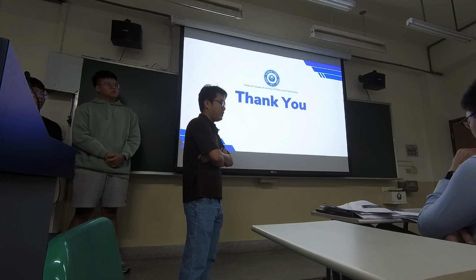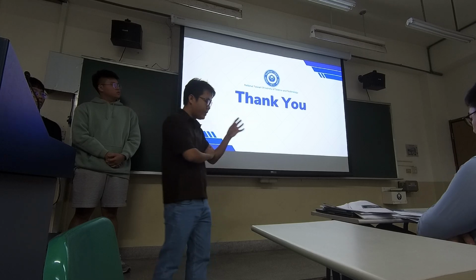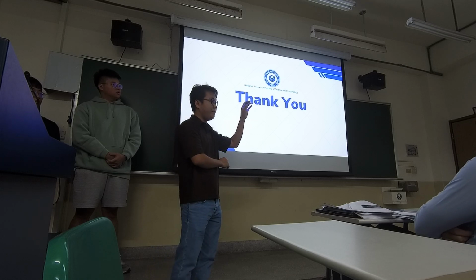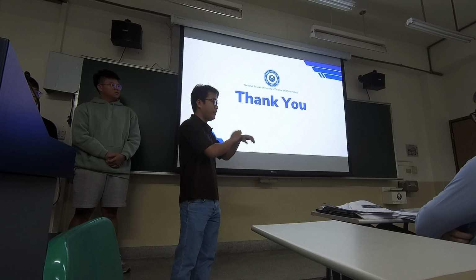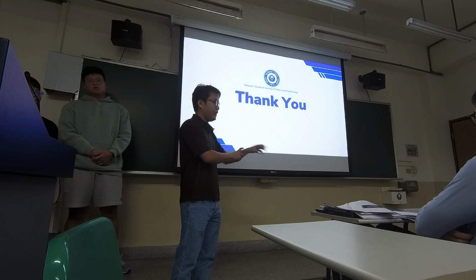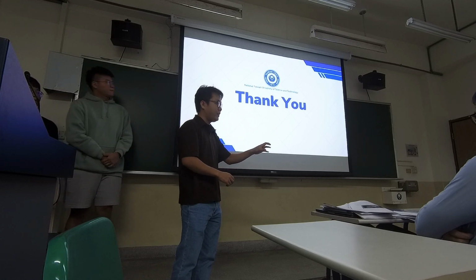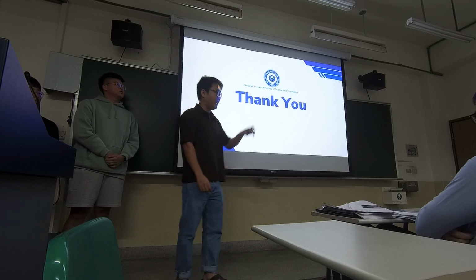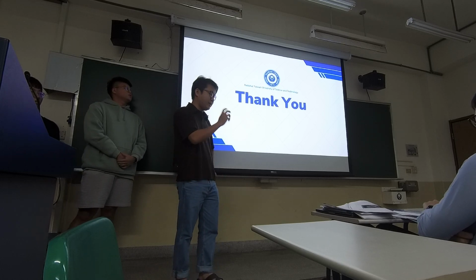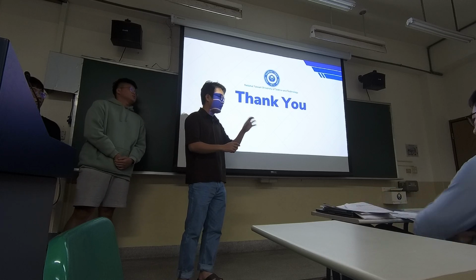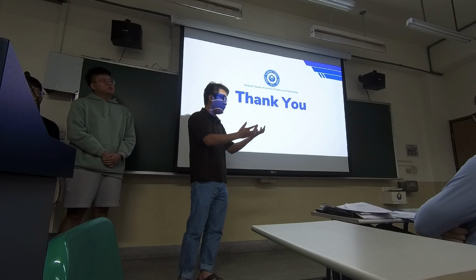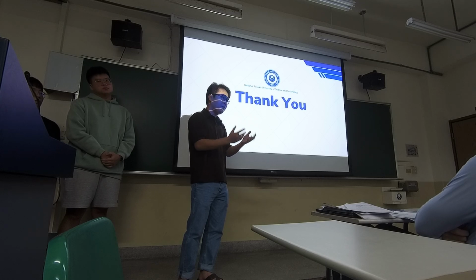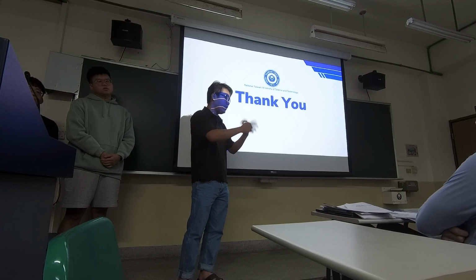So what's different? This one, he used the camera fixed in the base frame. Now I use the camera mounted on the robot hand, and we will track it online. And he used the Kinect camera, the point cloud is good, and now I use the RealSense camera. The point cloud is not full, it's poor. So you need to process something.